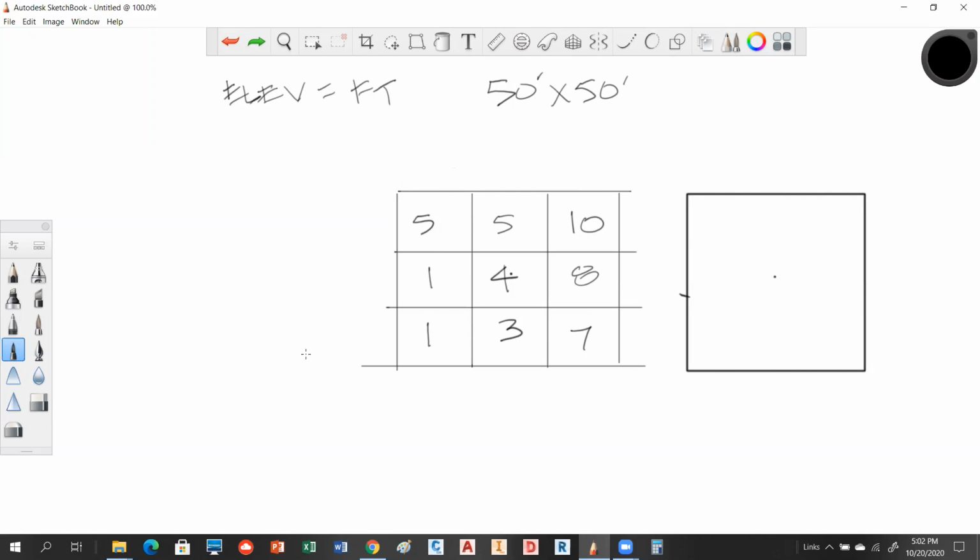Okay. So what we're going to do is calculate the slope, and we're going to do it in 8 directions. First off, I look at which way water would flow. So if this is my target pixel, in this case it's flowing in, flowing in, flowing in, flowing in, flowing out, flowing out, flowing out, flowing in. The reason I do that is because that establishes what we call the aspect, in other words, which way this thing is locally facing. Then we go through and calculate slope values for each one of these.